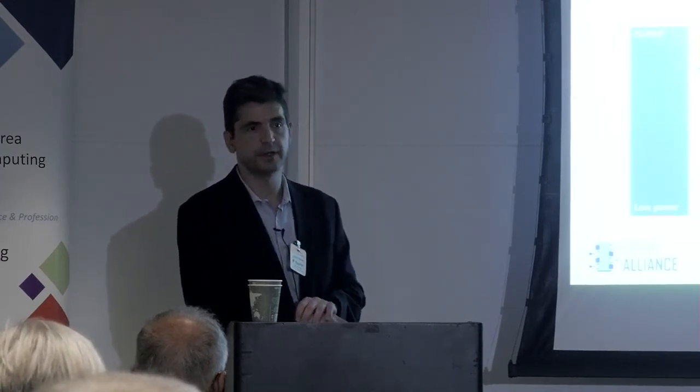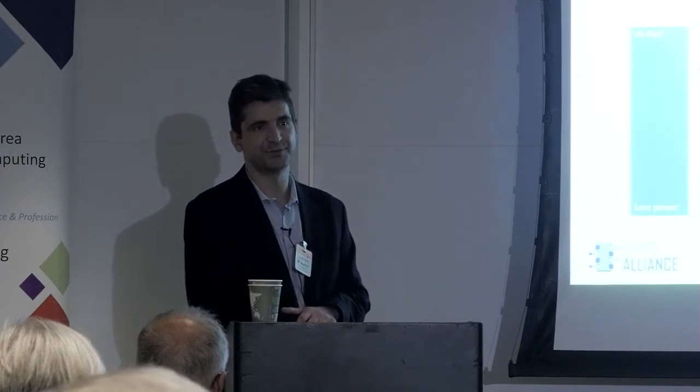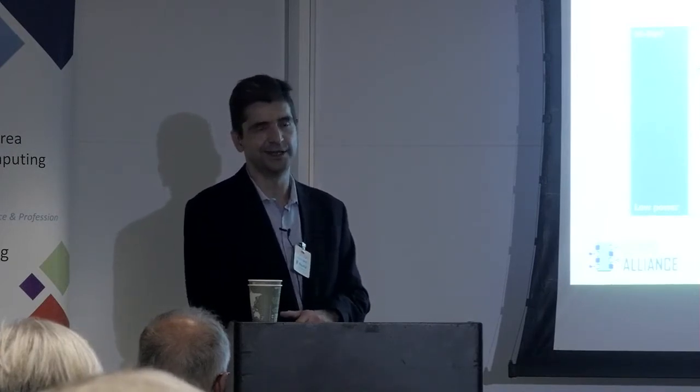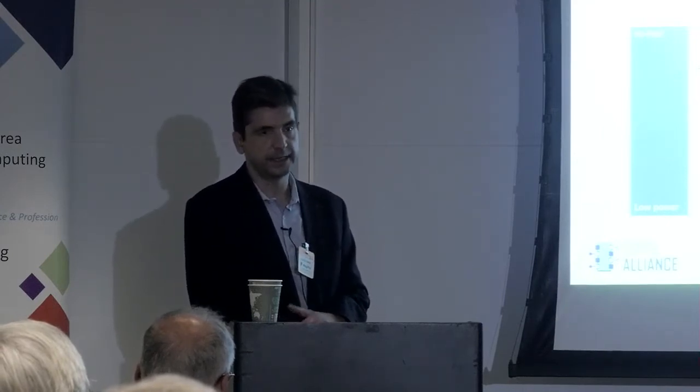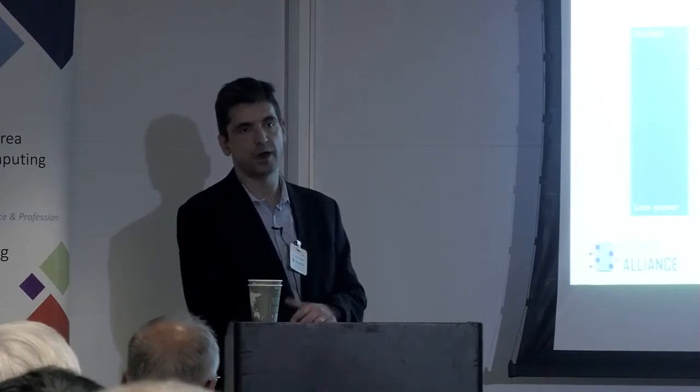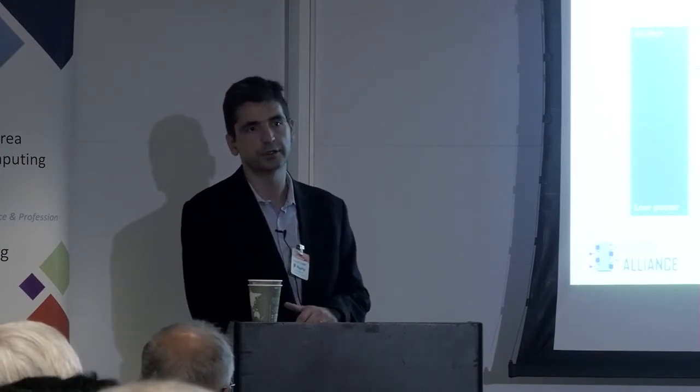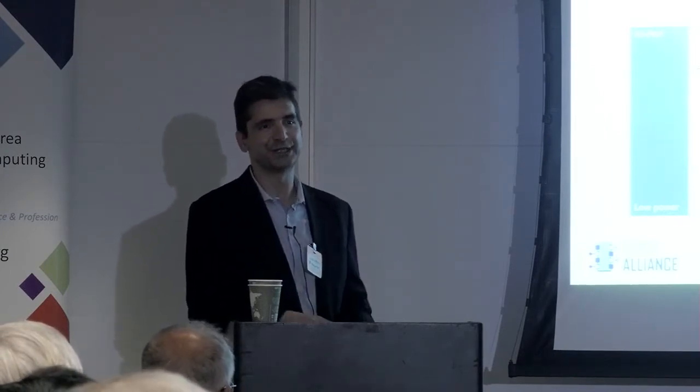The IP has been developed with design verification methodologies appropriate for CPU cores, which is very much tribal knowledge of how you do the random instruction stressing of the core, exploring all the corners in the design, mixing it with interrupts, mixing it with everything that's known from the history of previous projects to come up with a robust design. And then it's transferred as a verified IP to our ASIC team that's actually putting it in the product. So it's not an enthusiast core.